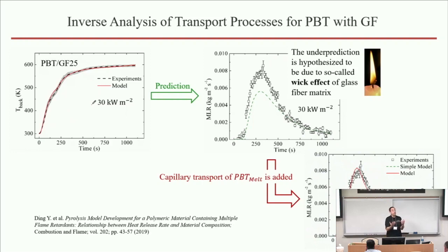Now this data contains information about that oxidative pyrolysis, and now you can make an assumption about what these oxidative reactions are. In the simplest case, you can say my char that forms as a result of pyrolysis will react with oxygen to form gaseous products, right? It's a simple assumption, and then you can parameterize these additional reactions based on what you observe in these oxidative experiments. So this is one way in which you can extrapolate.